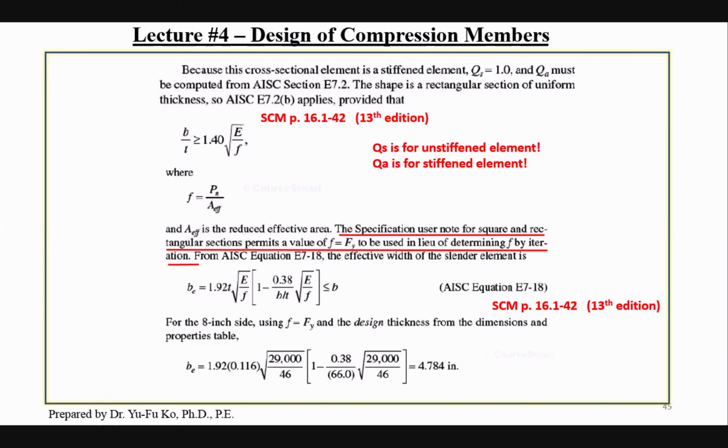For other sections, what do you mean by other section, Andy? If it's like a W shape, yeah, you use actual thickness, unless the equation requires you to use design thickness. They might have different definitions for different shapes based on the equation. Okay, excellent. It's very nitty gritty. There's a lot of side notes for the steel design code, so you need to pay attention to what it means and read it carefully.